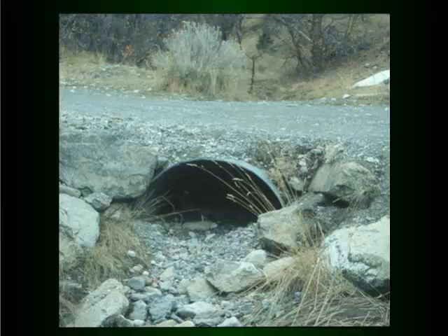Pipe filled with sediment, you probably lost 40% of the volume capacity on that one. That looks like it may have just been bed load movement down the stream, may have been natural. Maybe not a whole lot you can do about that except maintain the pipe, clean it out occasionally.